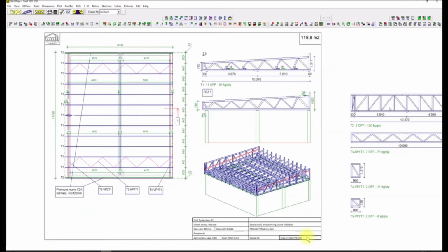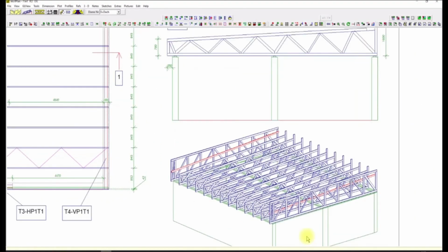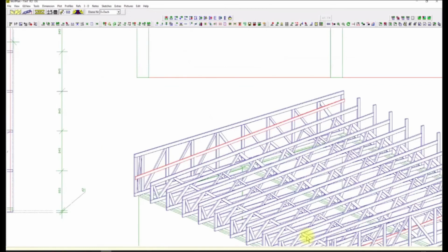And practically, this wind girder is on top of that, fixed to truss T5 on that side, and on the second side it is on T4 actually. Then it's a kind of wind box for these trusses, which fixes the full roof. The vertical wind girders are also set manually, so you need to know their dimensions, simply set the dimensions and insert them in the same way as you did for the top chord.